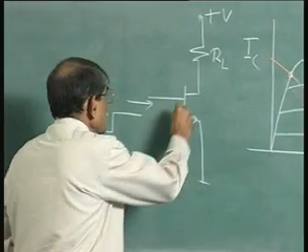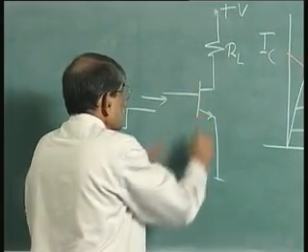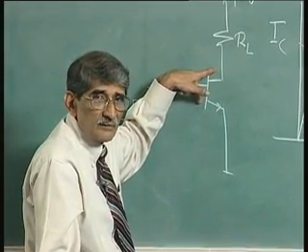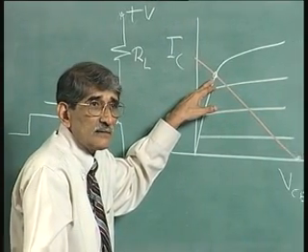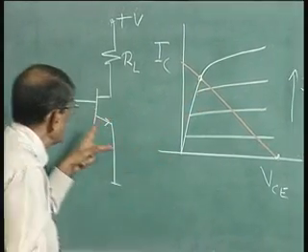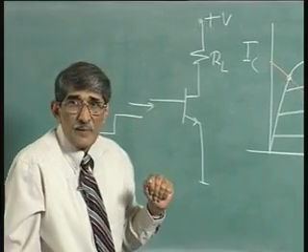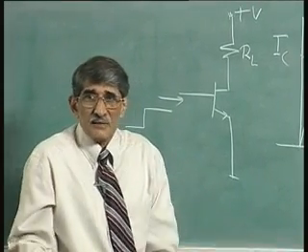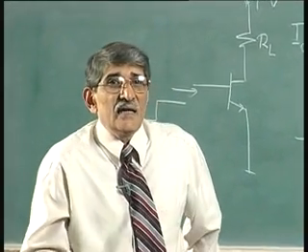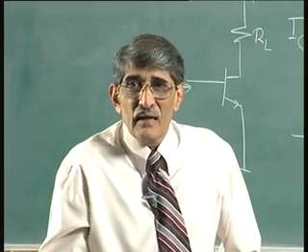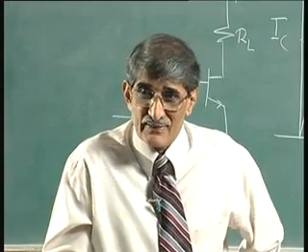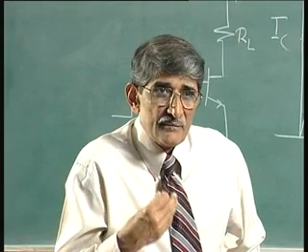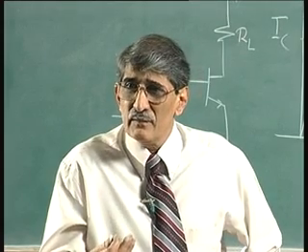So, what you do is, you prevent the transistor, when it goes into this portion, what is the state of voltage across the emitter base and collector base? When the transistor goes into saturation, the emitter base junction is forward biased, and the collector base junction also is forward biased. When it goes deep into saturation, the collector base junction voltage will be almost equal to 0.6 volts.